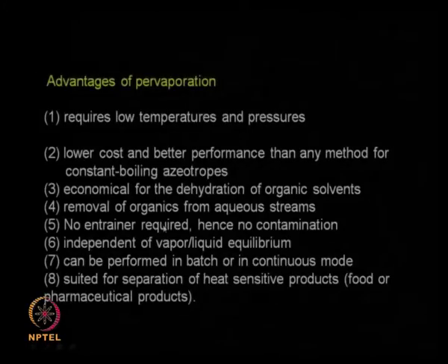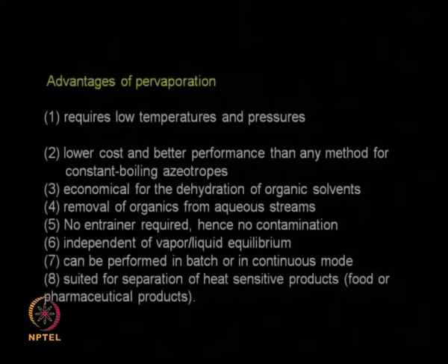You are not bothered about vapor liquid equilibrium here because the process is permeation and evaporation. So vapor liquid equilibrium does not come into the picture here. It can be performed in batch or continuous mode. That means we can do this operation in batch mode, or continuously you may pass a mixture and continuously be purifying the mixture.